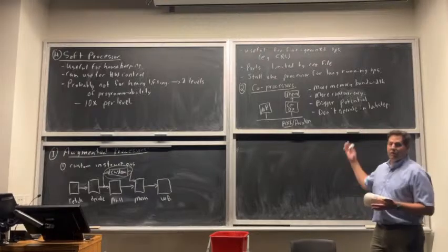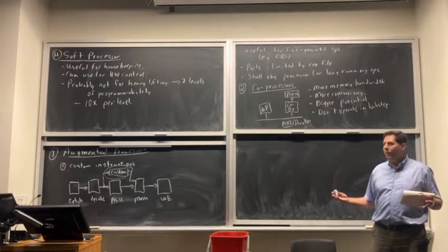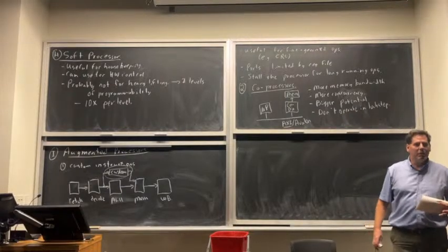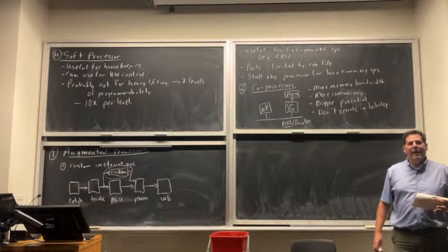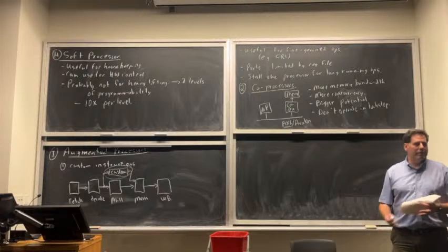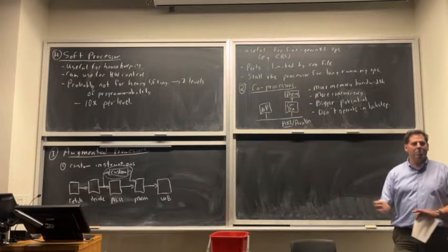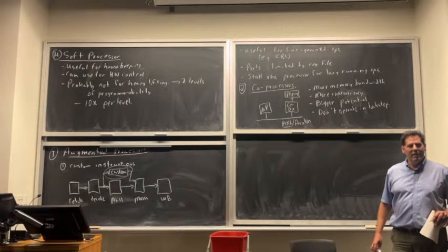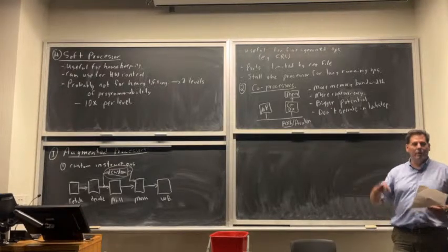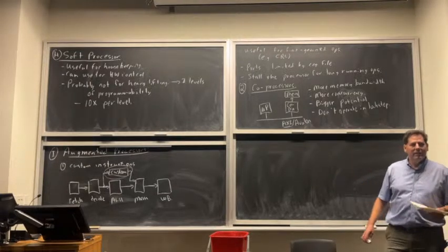And now that coprocessor can just go. It can read that data from memory as fast as it can. Let's say it's on-chip memory. Then we might build a 1,000-bit wide bus between that coprocessor and the on-chip memory. The coprocessor could be using the SIMD model, or it's a big pipeline of hardware that's able to process like 1,000 elements every cycle. It could be extremely fast. It might still take like 2,000 clock cycles, but that's fine. When it's done, it'll interrupt the processor, or the processor will read over that same bus some status register and realize it's done. Does that make sense?